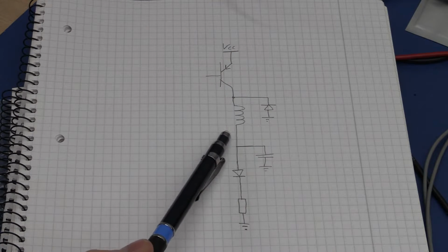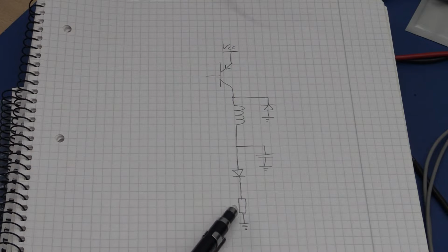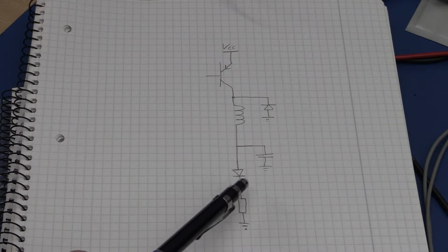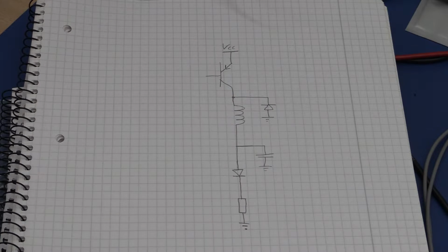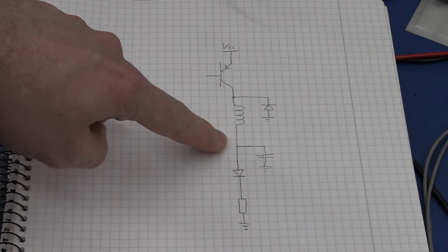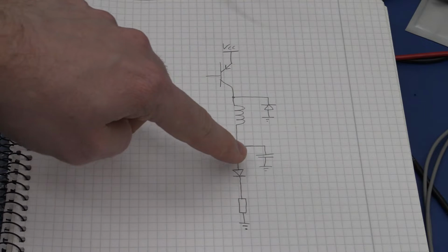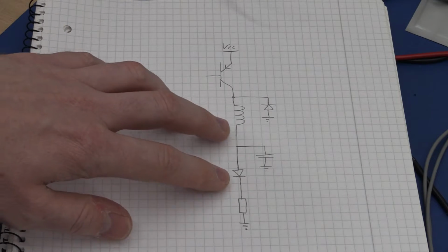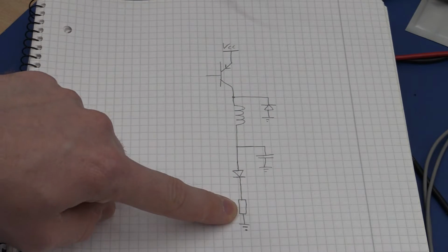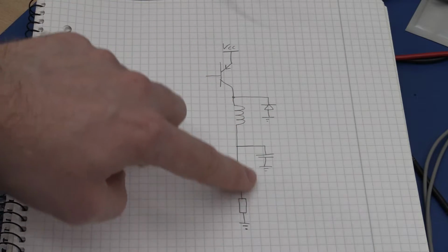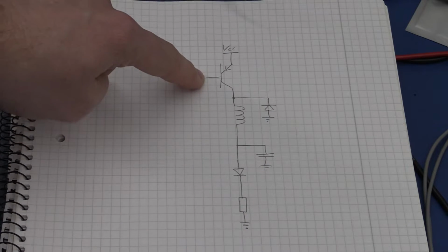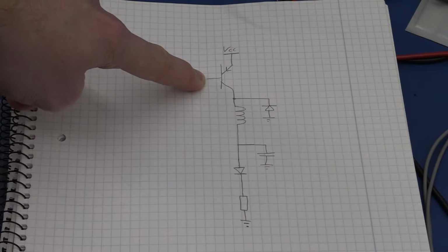So instead of measuring the output voltage, we will measure the output current by measuring the voltage across a sense resistor. So imagine we change this LED, we add more LEDs, less LEDs, put something else instead. The voltage here will change, but we keep the voltage across the resistor the same. So no matter what you put in here, you'll pull the same amount of current. The question then becomes, how do we drive the transistor?